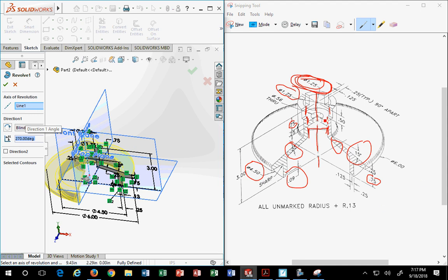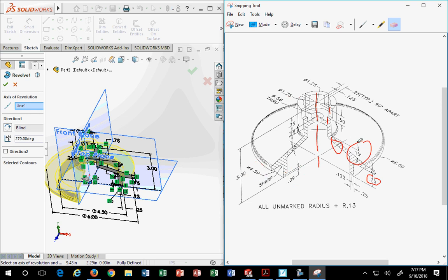But that's not what this part is sectioned for you. This part is not made to this shape. You can tell that this part is presented this way so that the user can use it to make the drawing. It is not physically built like this. It shows a sectional line in here. See these hatch lines all in here? All those hatch lines? That tells you it's a sectional view. The part itself is not made to that specification.